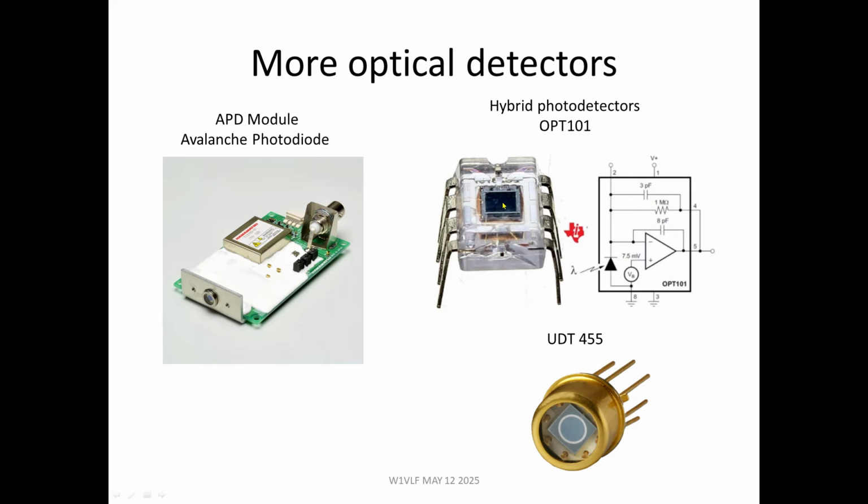The problem is that this detector is big enough, but these are like $1 a piece or something, and there's something called NEP, noise equivalent power. And what that means is, how much light power do I have to drop on top of this to equal the amount of noise that's generated by this solar panel? And these are not really, they're pretty poor. They also have a very limited bandwidth. But they're very convenient to use, and they're extremely cheap.